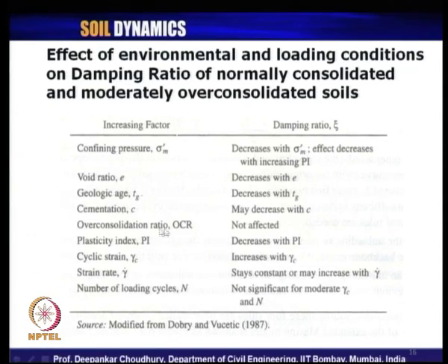What is the effect of over consolidation ratio? It was observed by the researchers Dobry and Vucetich in 1987 that OCR is hardly having any effect on the values of damping ratio. So, for different OCR values of soil, we can expect the damping ratio to remain almost the same. What is the effect of plasticity index? If plasticity index increases, damping ratio decreases, that we have seen just now in the plot also. What is the effect of cyclic strain? With increase in cyclic strain, damping ratio also increases. We have seen the pattern of the curve.